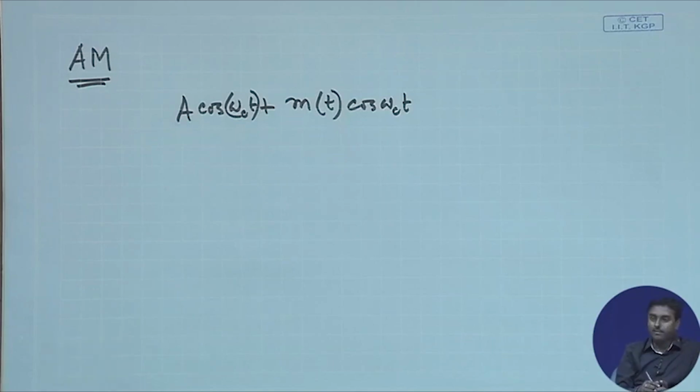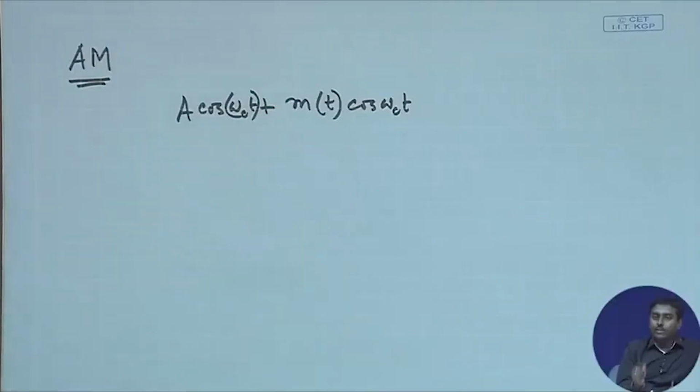It is a very simple one, but you will see that you get a lot of advantage out of it, and it is generally employed for broadcasting, because the corresponding receiver becomes very simple. So, we just add a carrier to it, and you will see that the entire complexity of recovering the carrier and then multiplying with a carrier just vanishes.